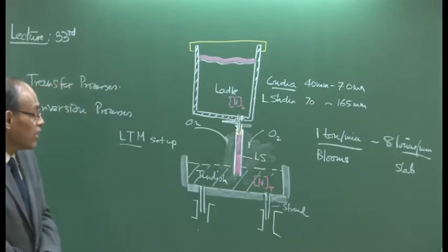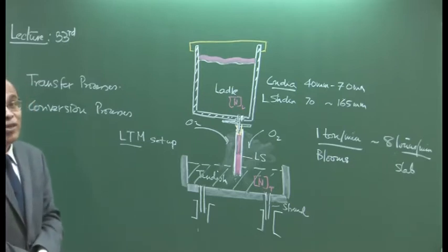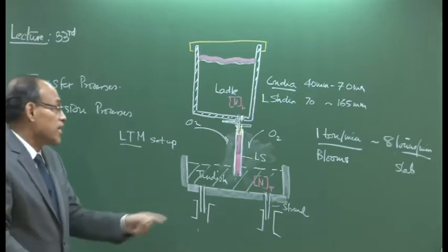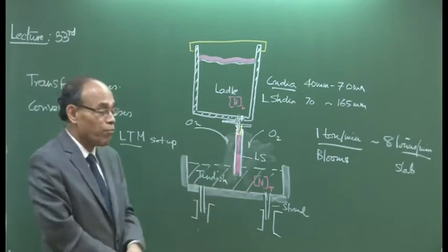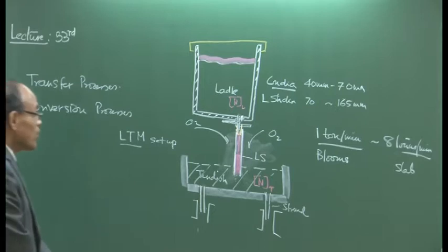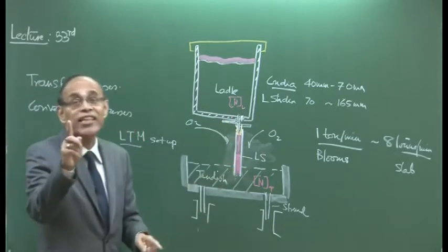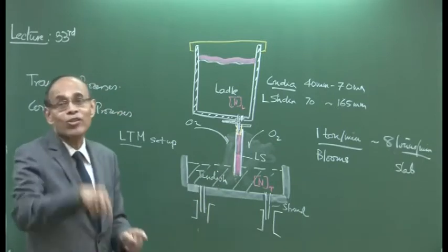On the other hand, if that difference is something like 20-30 ppm of nitrogen, then you can think the scenario is more akin to this kind of situation. But nonetheless, what is important is that any increase in nitrogen is an essential indication that molten metal has come in contact with the atmosphere.